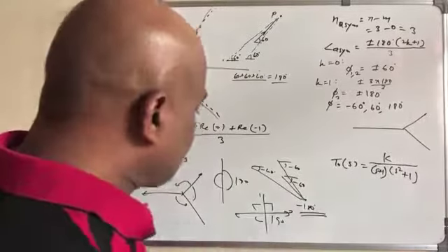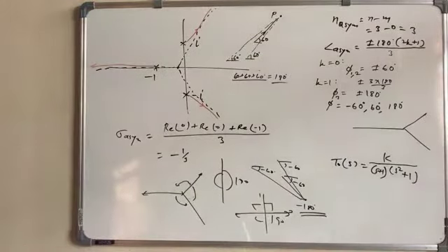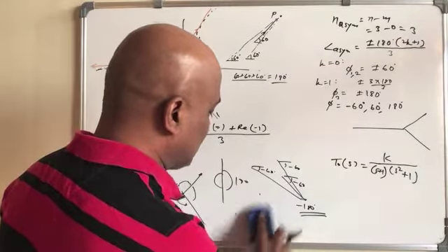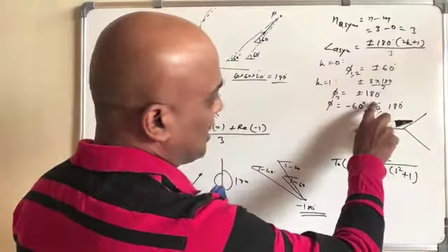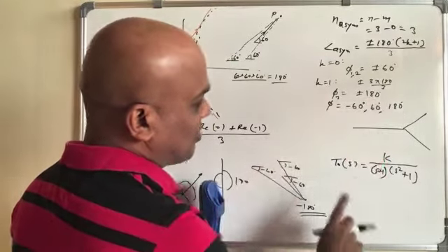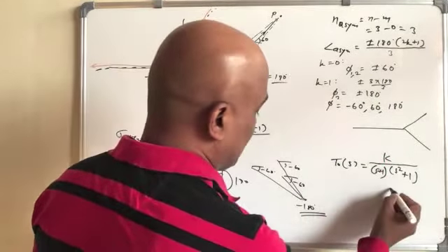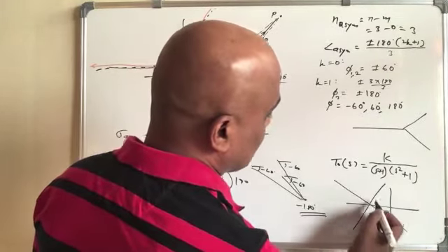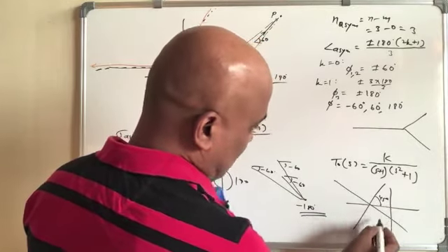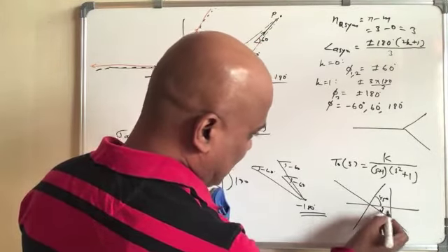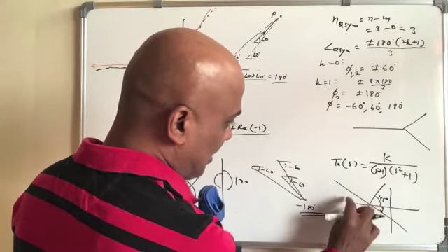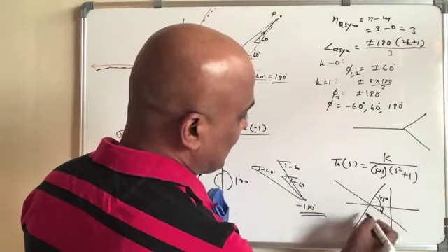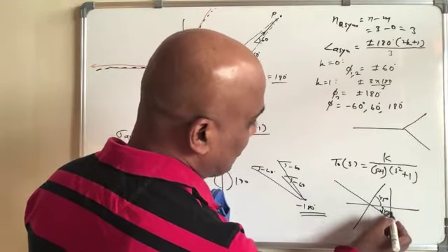There is one small correction though. This will not look like this one. If you have four asymptotes, then 180 divided by 4 becomes 45 degrees. So when you have four asymptotes, it will look like this, and you will have 45 degrees here. But it is still correct that there are equal angles between them. So this is 90 degrees, this is 90, this is 90, this is 90 degrees. But the orientation here will be 45 degrees.